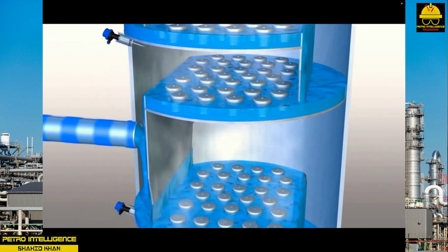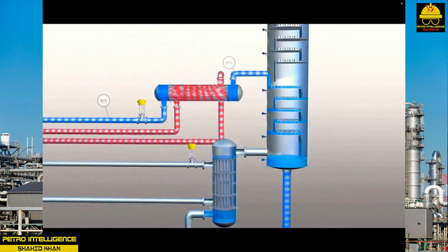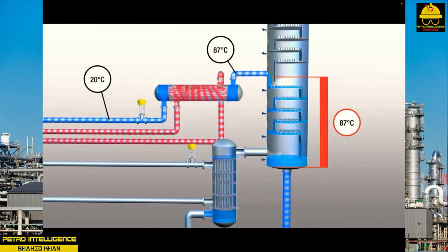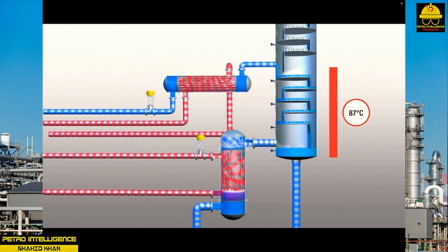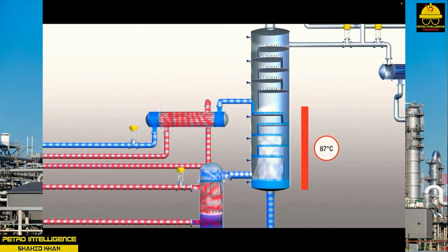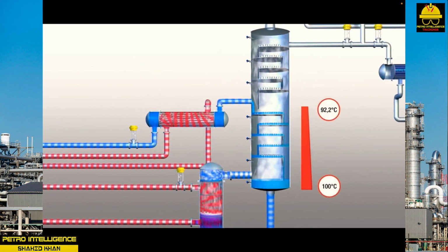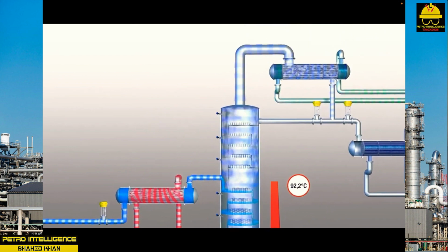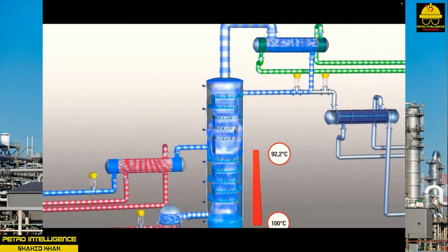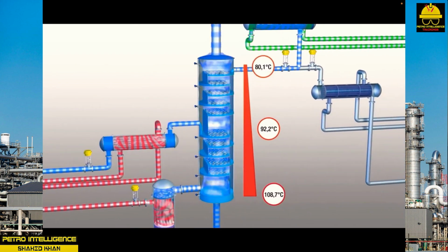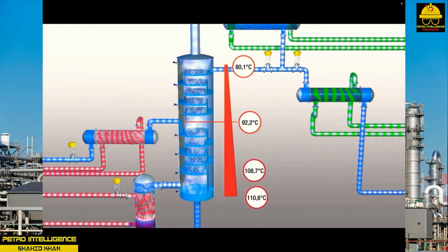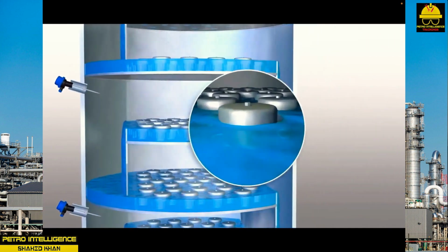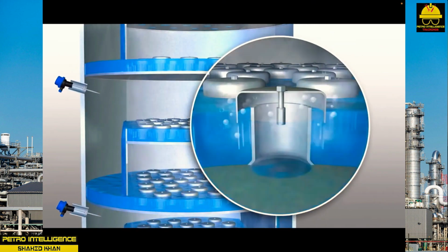A level control loop is used to keep the liquid at a predetermined level. In the bottom system, liquid level, temperature, and composition are carefully controlled. The overhead system is used to cool off the hot overhead vapors. The condensed liquid is used as reflux or is transported to the tank farm as product. Reflux is returned to the top of the column to control product purity and tower temperature.